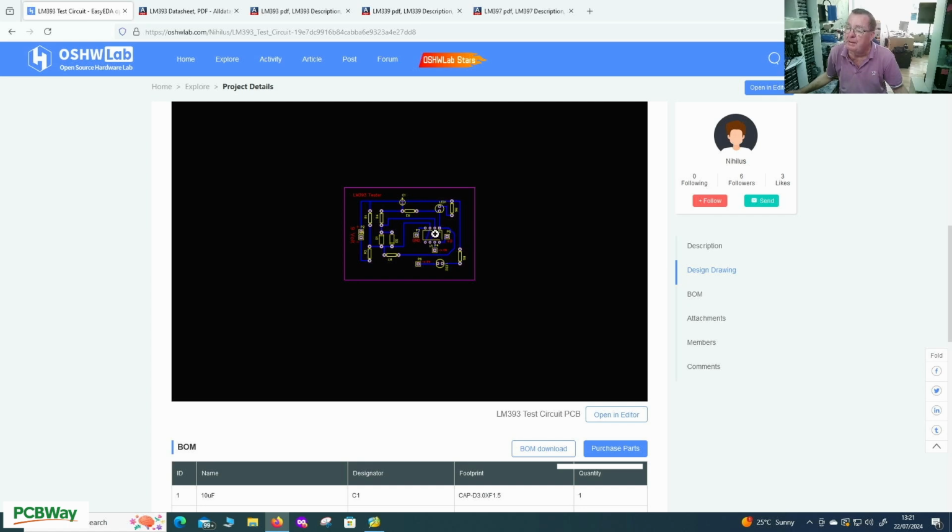And these are going from pins 2 and 3, which are the input on this side of the comparator, to 5 and 6, which are the input on the other comparator. Do you see that there? So it looks like basically they're using the same resistors capacitor network to test both of the comparators in parallel together. Now, I don't like this design.